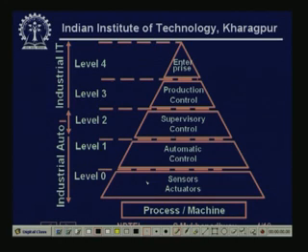Automatic control layers are also automated; most operations are not manually controlled. But from the supervisory control layer upward, it is not always true that you have computer based automation for performing the operations of that level. In fact, some of these operations may very well be done by human beings.